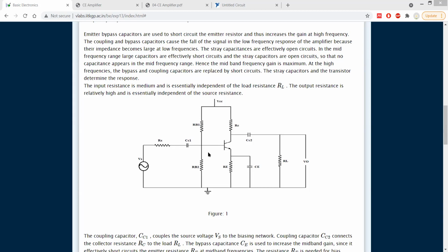So why so? Because there is a specific bandwidth. Whenever we design any amplifier, it should have some specific bandwidth. What does bandwidth mean? It means the amplifier will operate between a specific frequency region, amplifying those signals that lie between these two frequencies. The basic motivation for our experiment is to find the gain bandwidth, frequency versus gain.